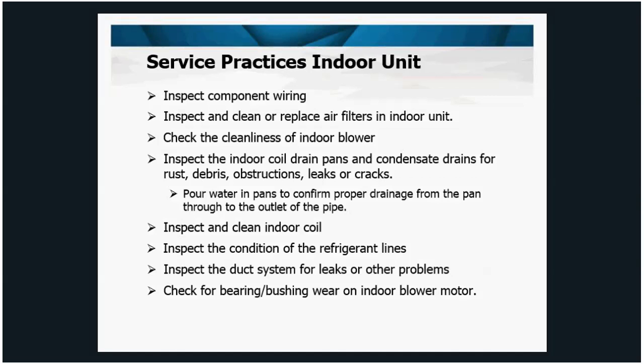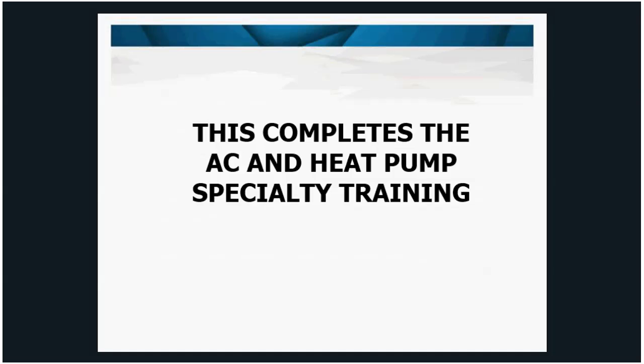Just like the outdoor motor, you want to check the indoor motor, check the bearings of those. Again, with the power off, try to move the shaft perpendicular to the motor. If you get that rattly feel, the bearings are wearing out, you need to replace the motor. And that completes it. That covers everything that you should need to prep for the AC and heat pump training.